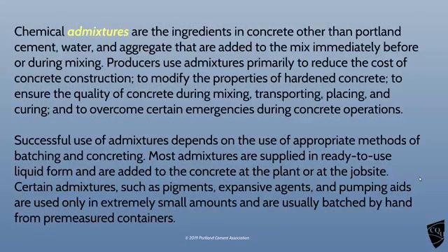So, admixtures, things you can add to your cement to change its behaviour and its properties. Some of them you can add before or during the mixing of them. They basically try to reduce the cost of the concrete construction you're going to do later on. It makes the concrete harden faster or slower, or makes it harden in hotter or colder temperatures when you do it, and it also improves the quality of the material itself, makes it easier to transport, easier to work with.